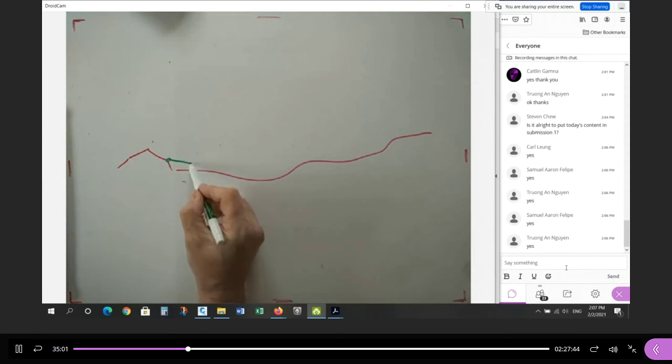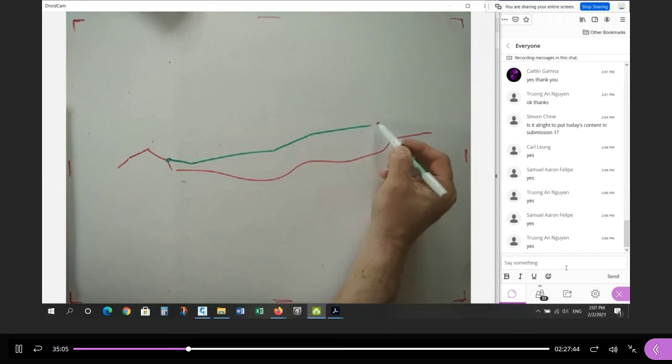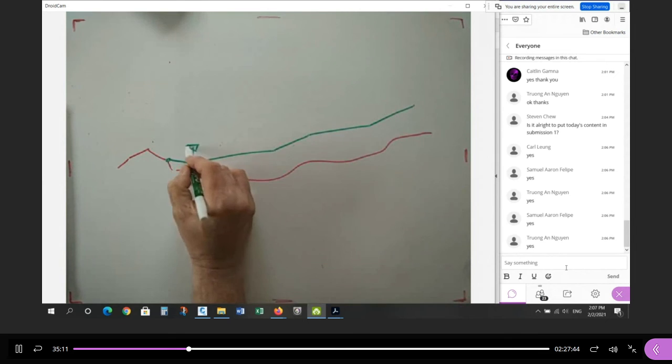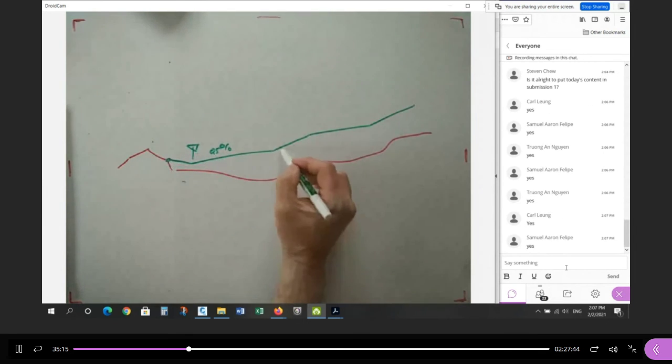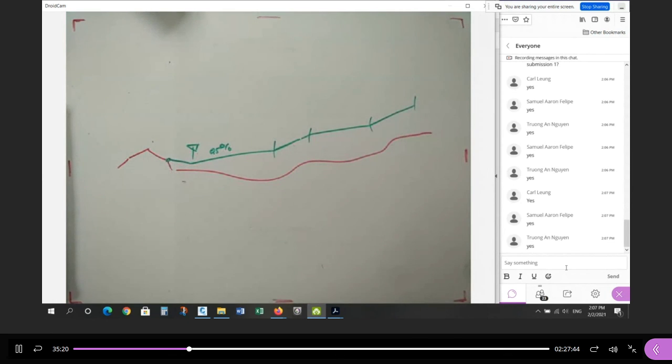And we went down to a low point, and then we came up. Then we went steeper through the elbow, then up at the minimum grade, and then steeper through the cul-de-sac. Do you remember that design? Does this sound familiar? Remember, we had a low point here. We had 0.5% typical. We went steeper through the elbow and steeper through the cul-de-sac. Everybody remember this, I hope? Fondly, no nightmares?